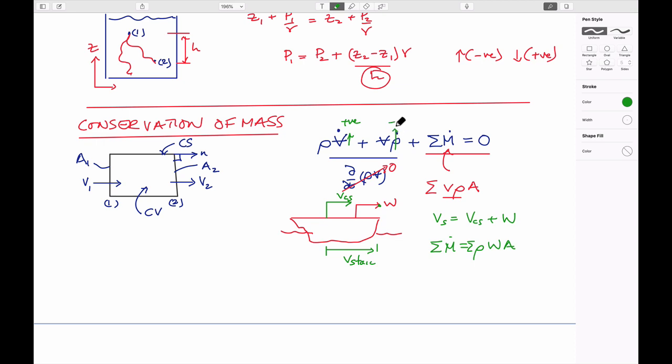Densities that increase are also positive. And mass flow rates out are positive, because the velocity multiplied by the dot product of the velocity and the normal to the boundary are positive on this side. So in terms of mass flow rates, if it's out across the face in this direction, then that's positive. And if it's in to the volume on the back side of this, then it's a negative magnitude. And these are always the summations of those individual components.